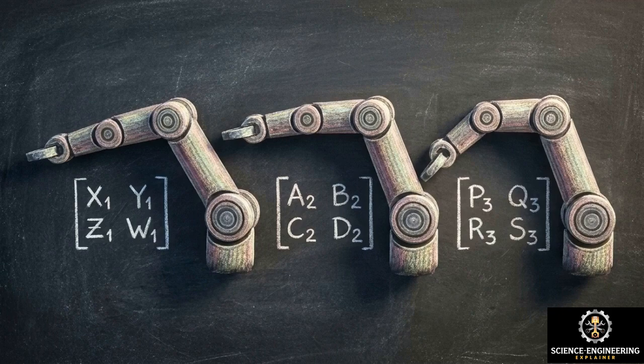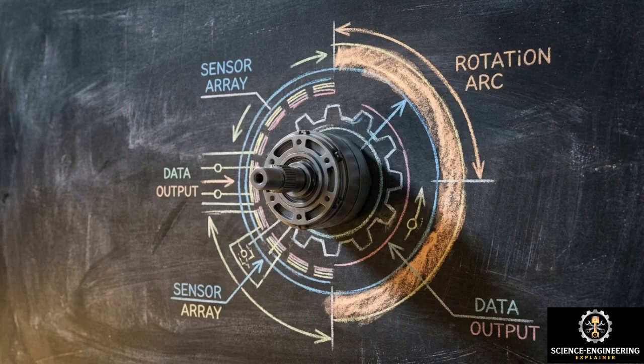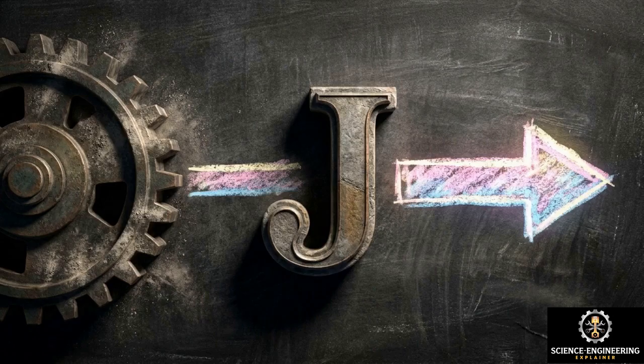There is a strict engineering rule for this equation. To yield accurate physical speeds, the incoming motor velocities must always be calculated in radians per second, never degrees. The Jacobian matrix operates as the ultimate dynamic bridge, allowing the controller to instantly translate internal motor RPMs into external Cartesian tip speed. We can pivot away from motion to examine static equilibrium.